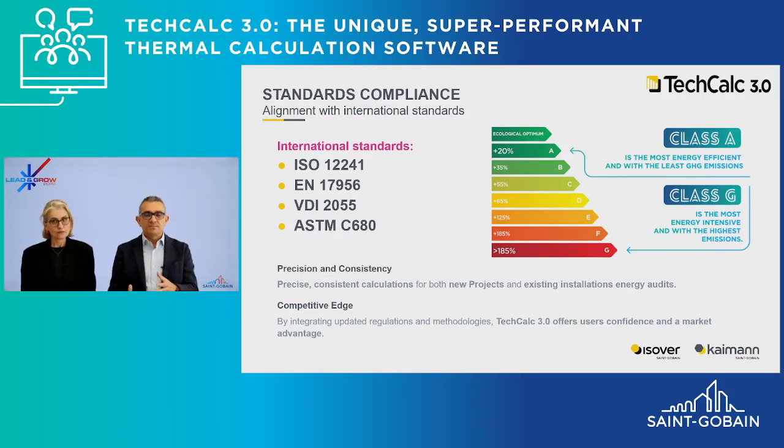Of course, in the second part, you can calculate the minimum insulation thickness if you have a target for energy efficiency class C. For example, class C or class D, it's possible to calculate for one solution what is the minimum insulation thickness.